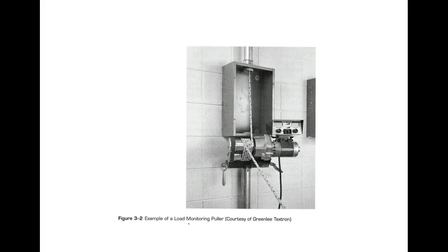Basically, the pulling devices that we use for fiber cable are basically the same as we use for copper. So we use fish tapes, we use cable grips or wire mesh grips, and this is what I showed y'all. But we never pull with the fiber conductor. We always pull with the outside jacket and mainly the Kevlar.